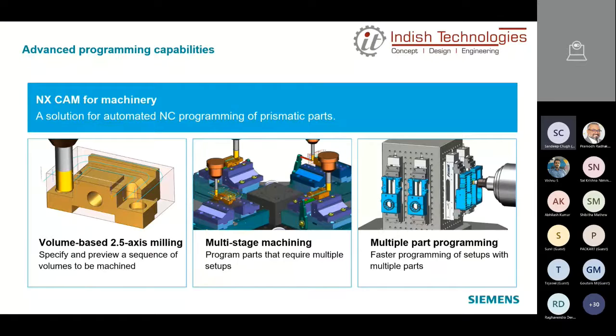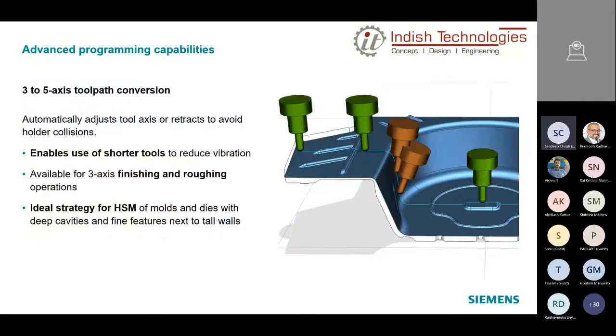No restriction. Let's say you have generated a 3-axis toolpath. You can convert that 3-axis toolpath to 5-axis without having mill multi-axis. With only the mill contour category of sub operation, you can tilt the toolpath if your machine permits. You have the software for 3-axis, the machine for 5-axis, you can convert a 3-axis operation to a 5-axis operation using toolpath tilt. If you have mill multi-axis, that has many advantages, but even a 3-axis toolpath can be tilted for 5-axis machines.